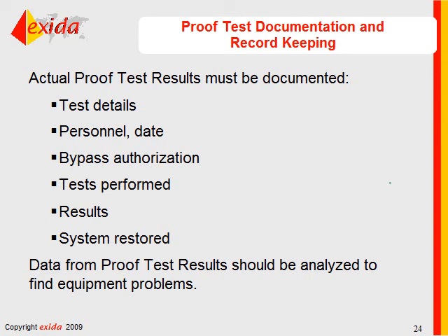So this is basically, in a nutshell, things to look at when it comes to proof testing. And yes, there are other aspects. People may want to make sure that when they perform the proof test, the application software in the logic solver is still the same, though theoretically the checking of the application software, making sure that the version is the same, will not detect any dangerous undetected failures in that particular logic solver. It's just a test of whether your modification procedures are acted upon, if people are doing what they're supposed to do.